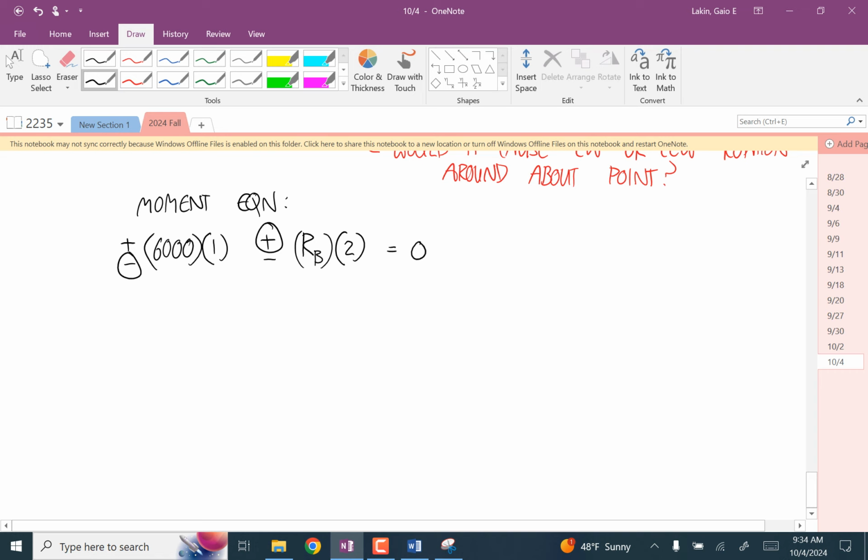So for these horizontal beams, in a lot of cases, setting stuff up in terms of vectors and doing the cross product is the quickest way. But with horizontal beams like this, it's not really worth going into the vectors. You can get through these a lot quicker by just thinking of the distances. Okay, any questions about that?